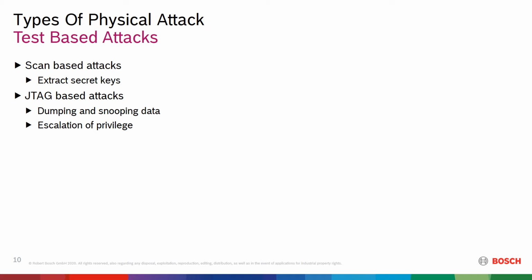And then you have JTAG-based attacks. If the JTAGs are left open in the devices, they could be used to dump the memory contents and reveal the key, or reverse engineer intellectual property, or bypass security features, escalate privilege, and so on.